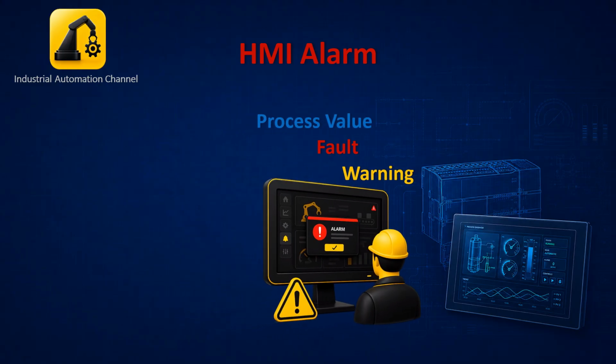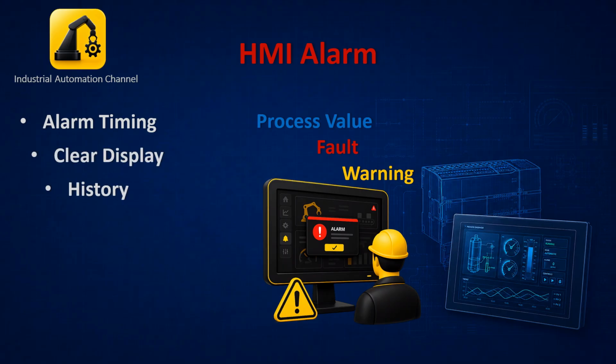First, you need alarms that appear at the right time. Then you need to show them clearly to the operator. After that, you need a history of what happened before, not only what is active right now. And finally, you need the right operator actions like acknowledge, silence, reset, and later also a buzzer.